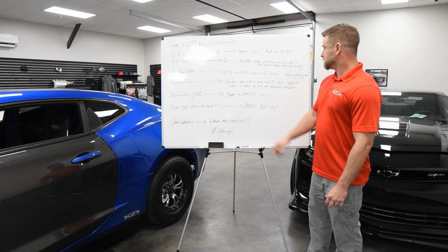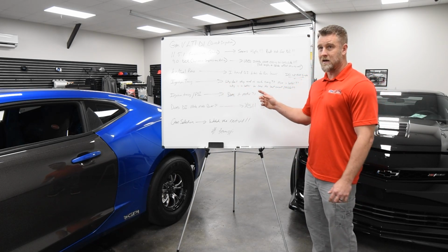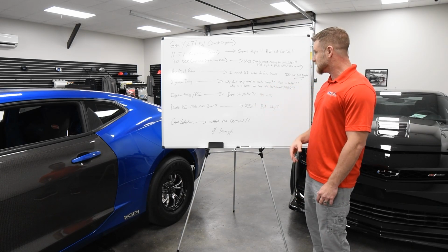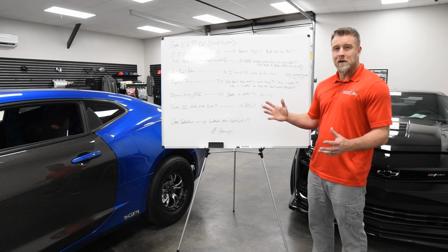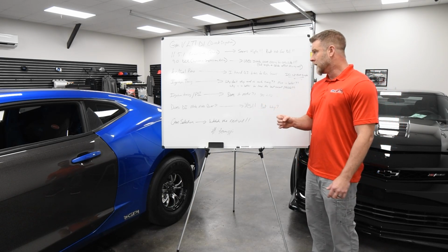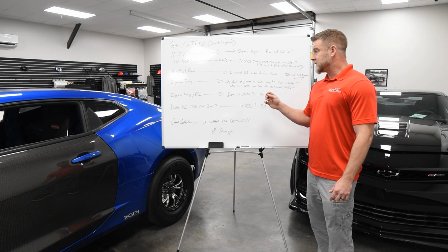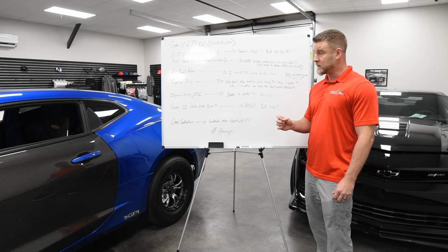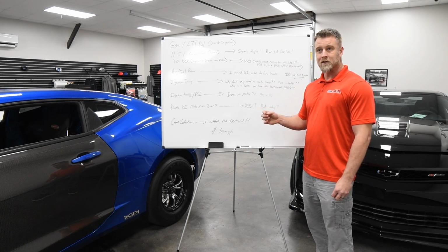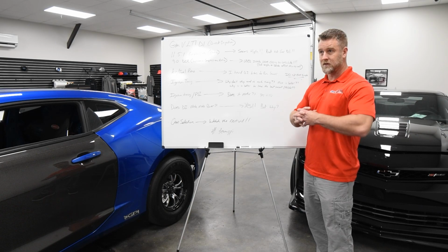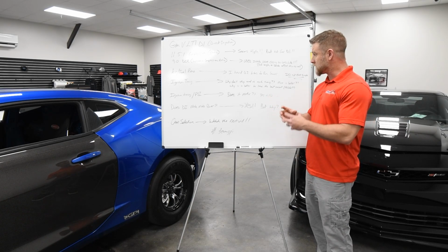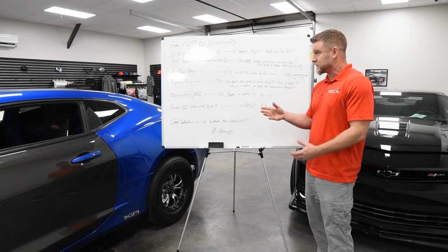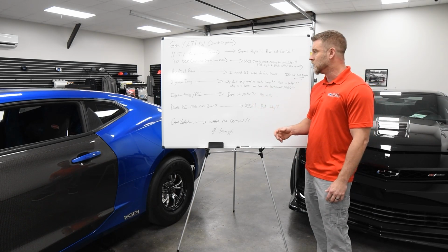Ignition timing. Why don't they need as much ignition timing as our LS counterparts? More is better, right? And why is it better to have the least amount possible to get the job done? The LT combustion chamber, coupled with the fact that it is a higher compression ratio, coupled with the fact that it is DI, it has an optimal fuel mix and atomization, it doesn't need as much ignition lead advance to fire off, to make max power.